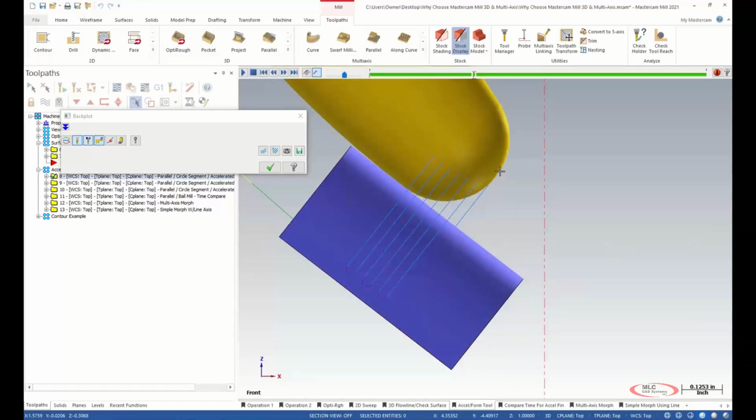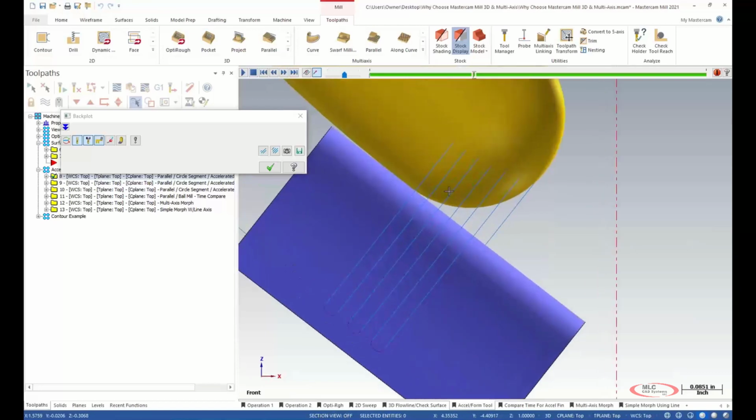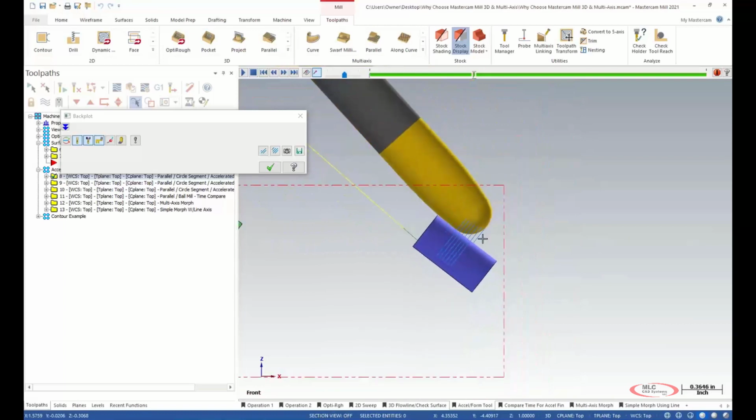So if I was running a ball mill on this, the only contact I'm making is with the very tip of this tool. And theoretically, running the tip of the tool is pretty much at a 0 RPM point, being right in the center. So in this case, we would probably still tilt the tool to stay off the center. Now, what you notice about the form tool is no matter the radius of a ball mill, I'm always going to be running on a point. In this case, we start running a larger radius. So even if I have a 1/2 inch diameter ball mill versus a 1/2 inch diameter oval form tool, instead of having a certain size radius, I can give it maybe a 3/4 radius on the side. So it's not driven by the diameter of that tool.